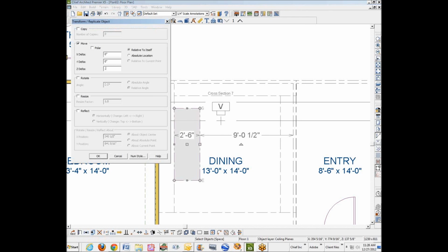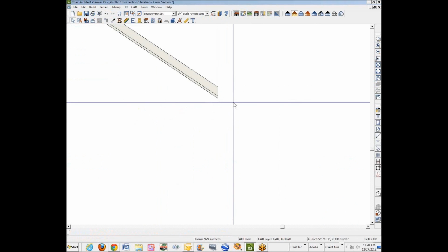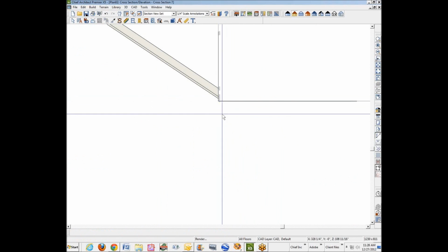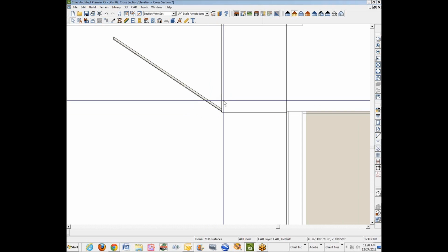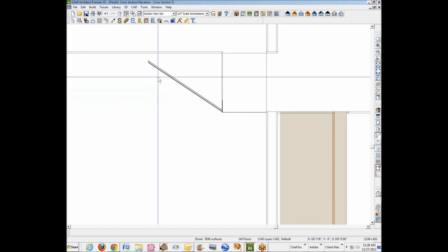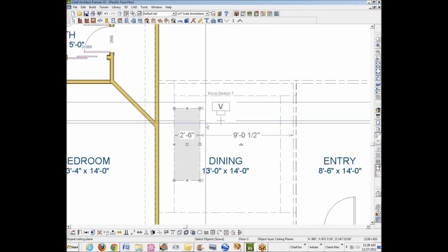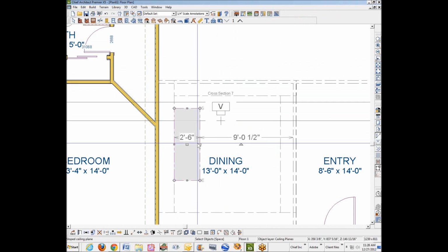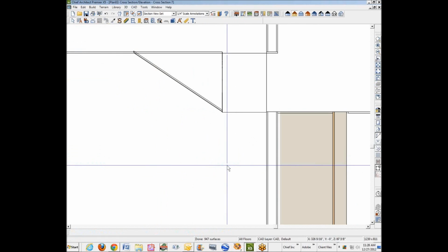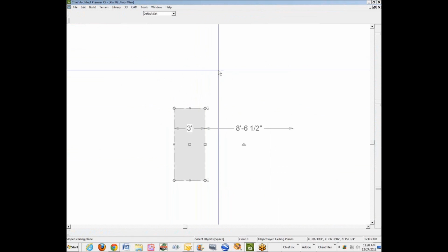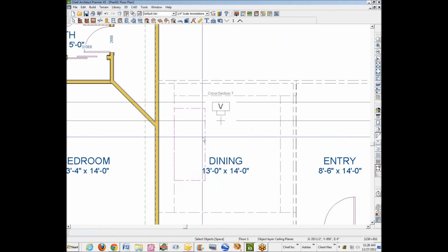0.5 this time. So I get the first one in, and then I just copy paste them once I've got them the right z-axis height. That's fine. You get the idea. You move transform replicate to get that thing about where you want it. For me to hit my 11-foot ceiling, I need more than 30 inches. So I'm going to set that to 36 inches and check it in the camera. Yeah, that's good enough. Okay, now we're in business.